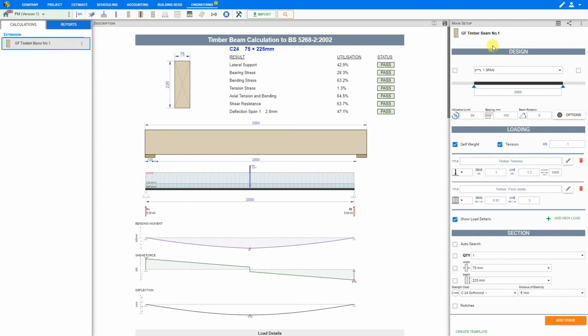If we decrease the number of beams, then we need a wider and deeper section to satisfy the structural checks. Based on the rest of the input in the previous sections, if we click Auto Search only for the depth, then the calculator will optimize the depth for a given width.